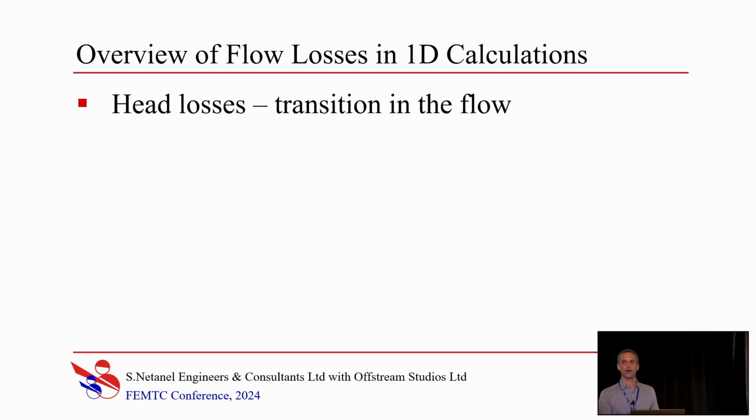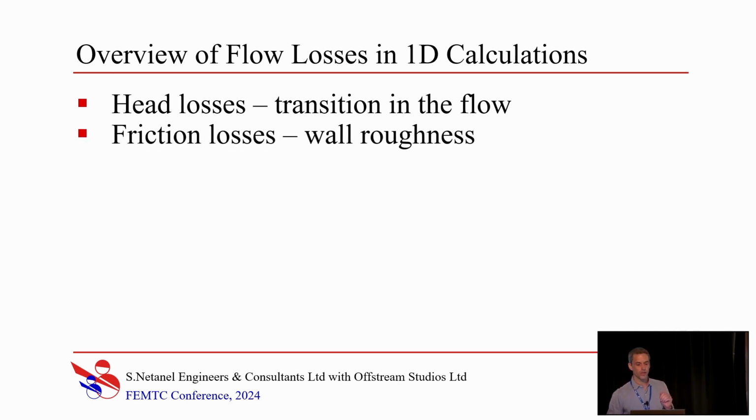Now, ducts are representing both tunnels and stations, and the loss associated with ducts will be friction loss due to wall roughness. Now, I was looking at the parameters, I was looking at friction, and I saw that the friction between tunnels and stations is not that different. Considering that stations are much shorter than tunnels, that difference should be even smaller. So theoretically, I could use a single duct to represent both tunnels and stations, and I would get almost the same friction.